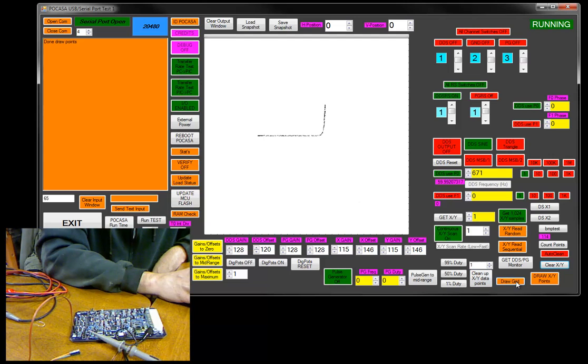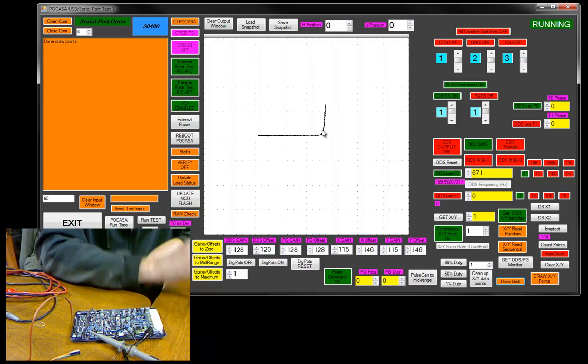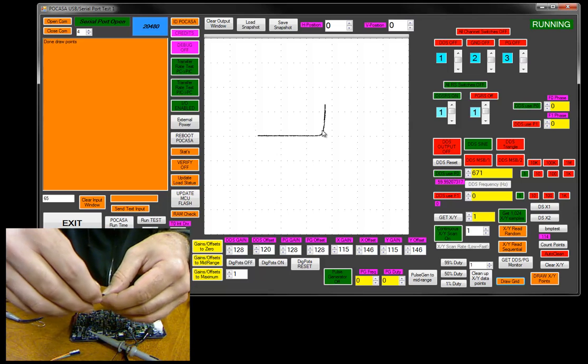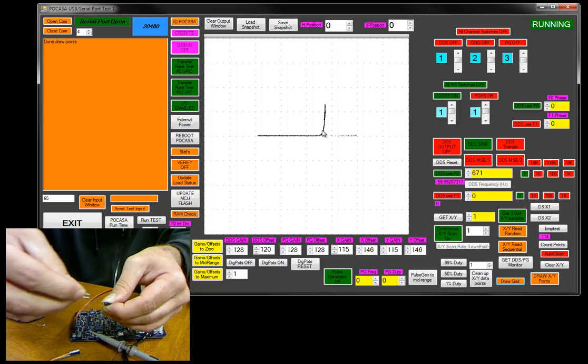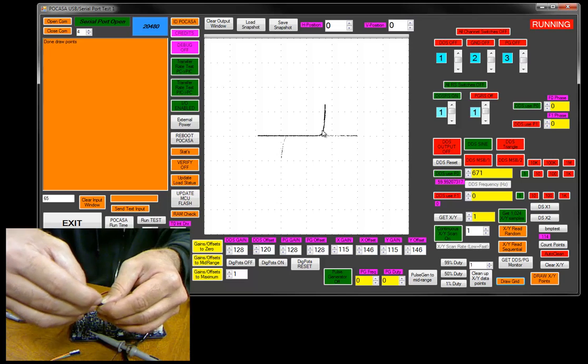Over on this side is the negative side. This is where all the voltage going through it is negative, so it's not conducting anything. And as the voltage goes positive, the current flowing through it gets higher and higher. Here you go. So if we turn the diode around, we'll show a curve going the other way. I just turned the diode around.